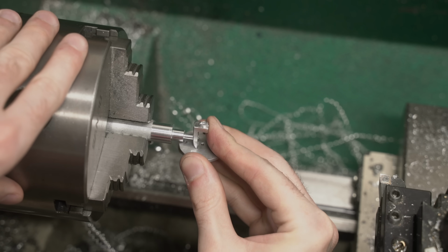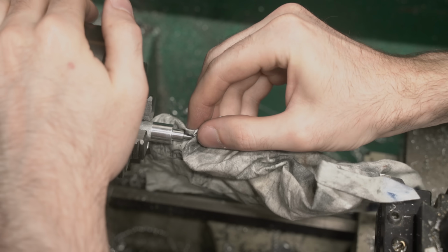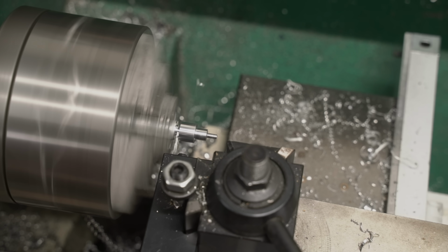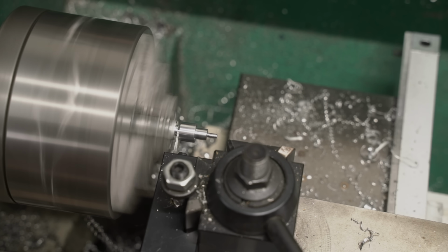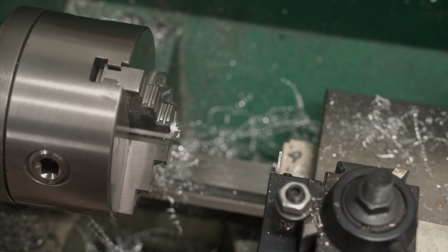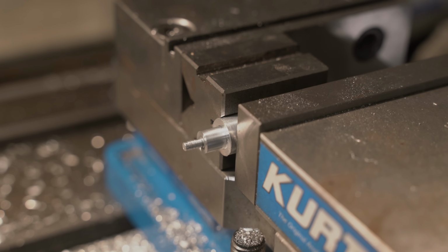It's close, but a little snug. A little bit of sanding with some 1000 grit sandpaper should do the trick. That's more like it. Now I'm going to part off the mirror. However, I'm including a large chunk of extra material because we need to have something substantial that we can hold in the vise. If we don't leave this part, we'd be forced to hold it by the tiny shaft, which is far too small to withstand such abuse.